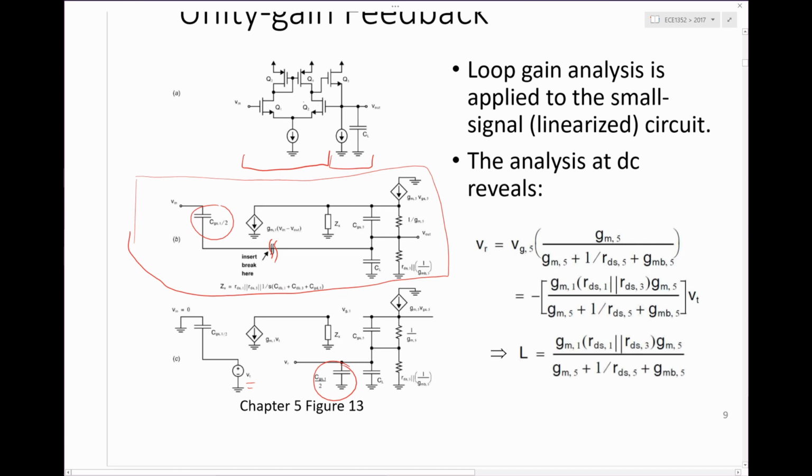It's all good. In practice, though, we have the problem I mentioned before. We have to be careful because obviously Vin can't just be a small signal like that. It needs to be DC biased a little bit above ground, say about a volt above ground, in order to allow some voltage drop to appear across the tail current source, and also to allow for some VGS across Q1 so that the transistor is actually on. So we need some bias voltage here, and there needs to be a corresponding bias voltage here. If we break the loop, we have to find some other way to establish all those bias voltages. That's the discussion we already talked about. But here in this picture, it's just a paper and pen exercise where we work on the linearized small signal circuit, and then it's clear what we need to do.